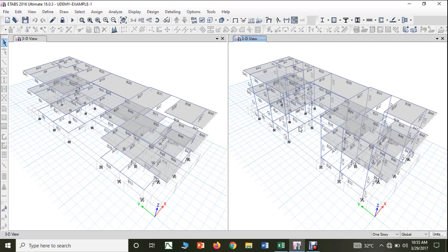The main two reasons why we provide plinth beams: the first and foremost reason is to make the slenderness ratio of the column lower, thereby making the column stiffer. Not only that, the entire structure also becomes stiffer. And anyhow, the plinth beams provide a support to construct the walls. Therefore, usually the dimensions of the plinth beam are small, as well as the reinforcement provided to the plinth beam, right?